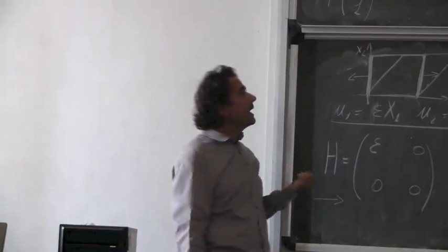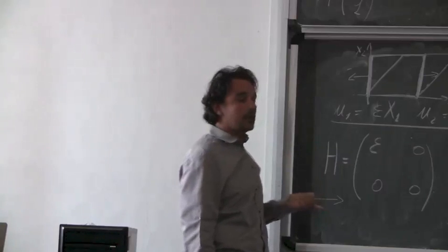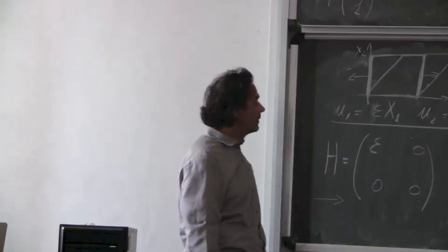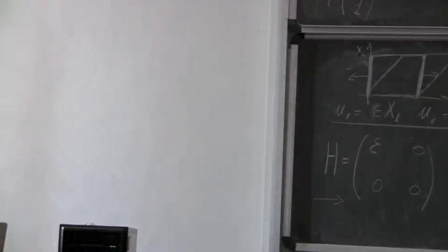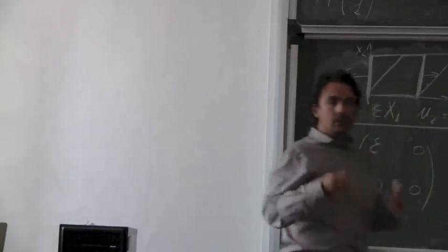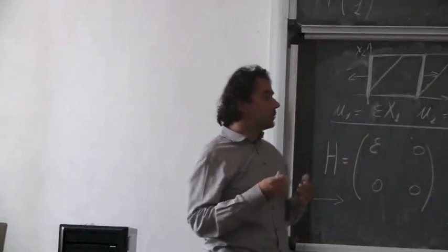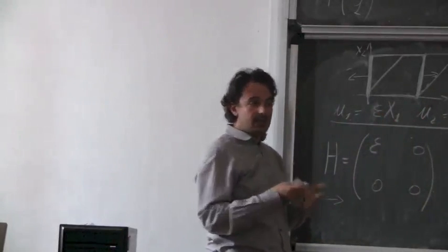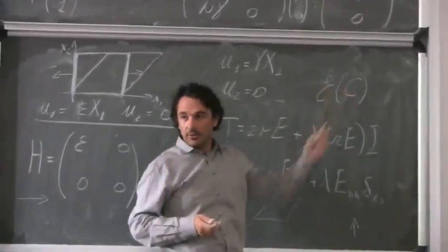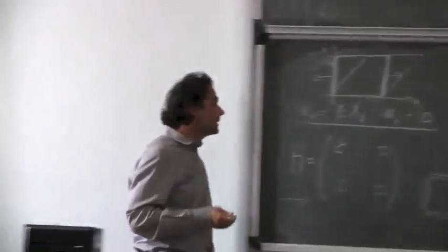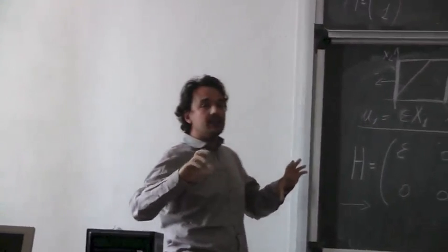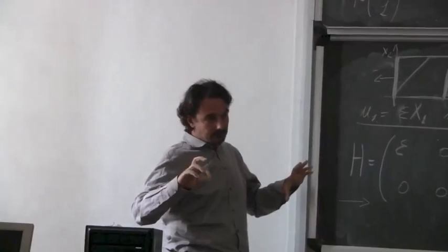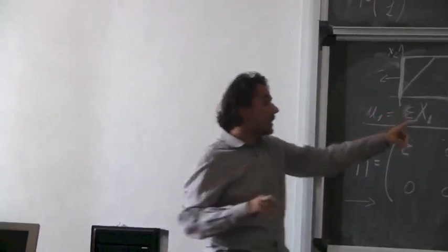So we have derived the partial differential equation for a first gradient material in which the internal energy depends on E. If you want to consider a material with higher order gradient, you have to consider a different constitutive equation for E. But then you can see that because we make this derivation by parts, here we have only one derivative with respect to x.